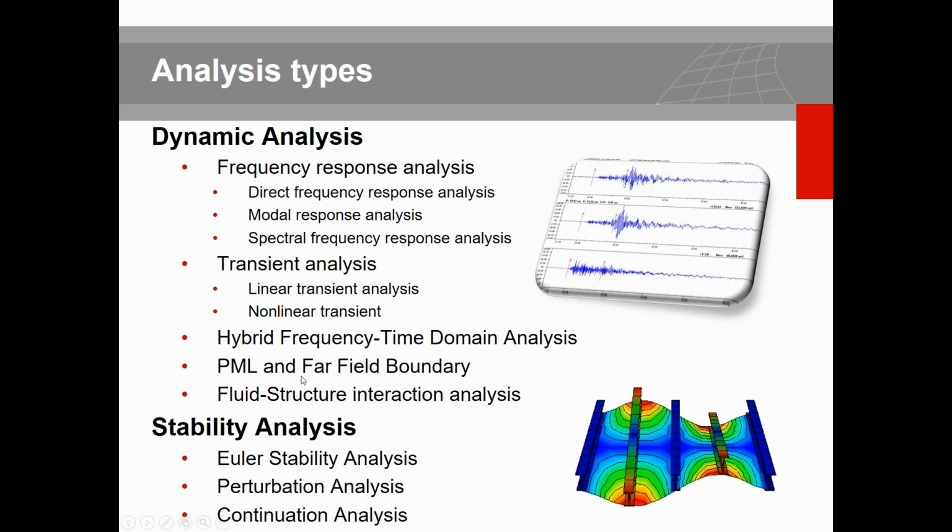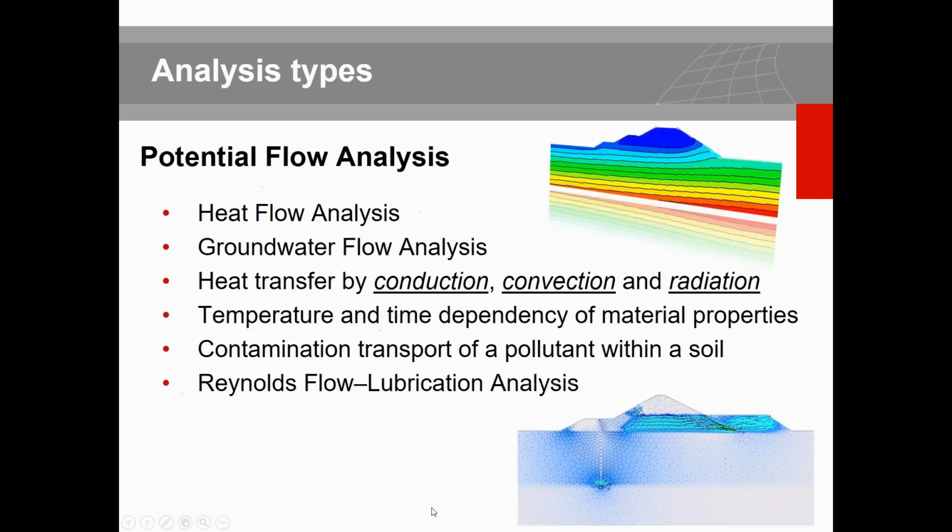And also for transformation of the mass of the reservoir or fluid domain in the tank or in a reservoir of the dam or some dikes, you can use fluid structure interaction. This mass automatically gets transferred to the body, to the structure, and as a consequence of the time series analysis, you can obtain the hydrodynamic pressure acting on the model. You can use Diana for general buckling, post-buckling, and also perturbation analysis and continuation analysis as well.